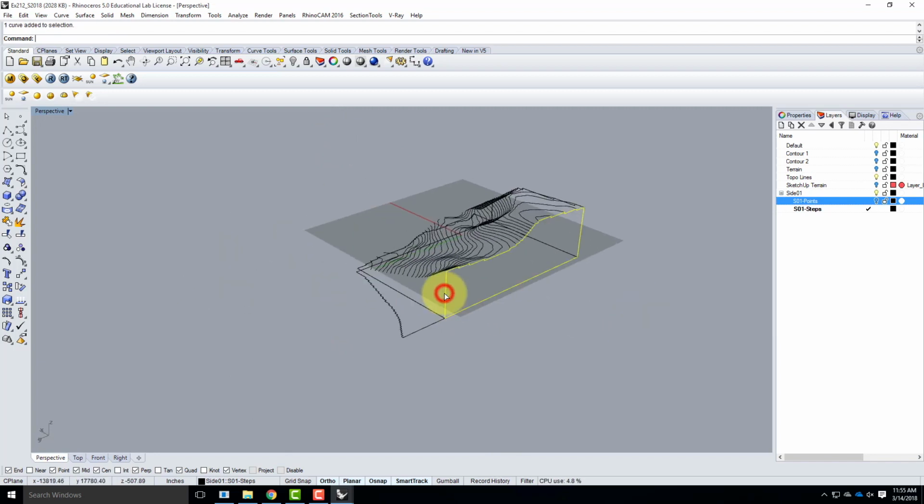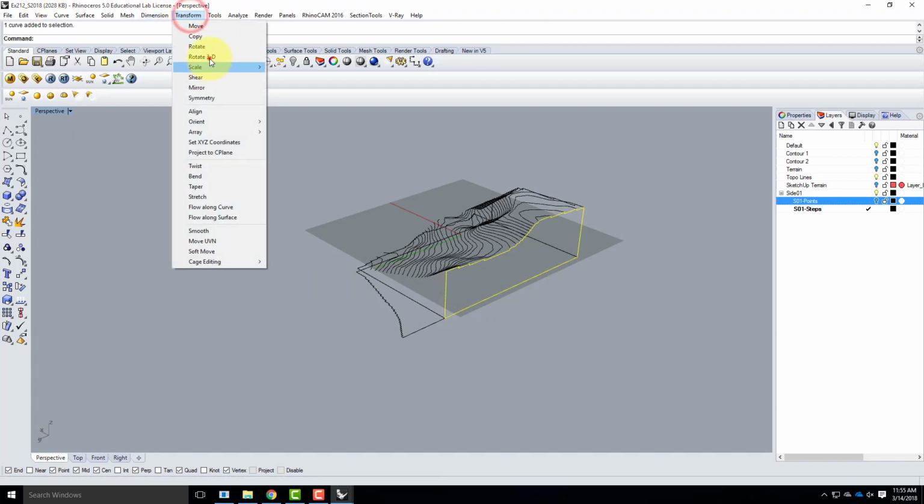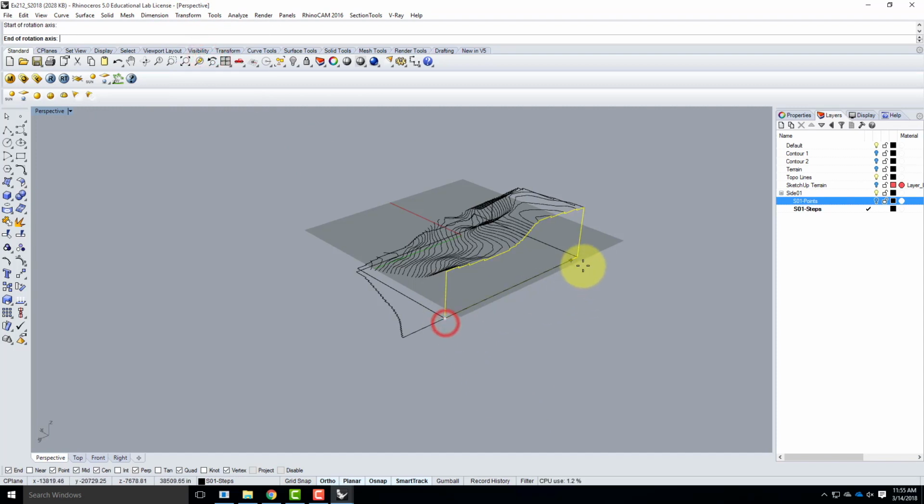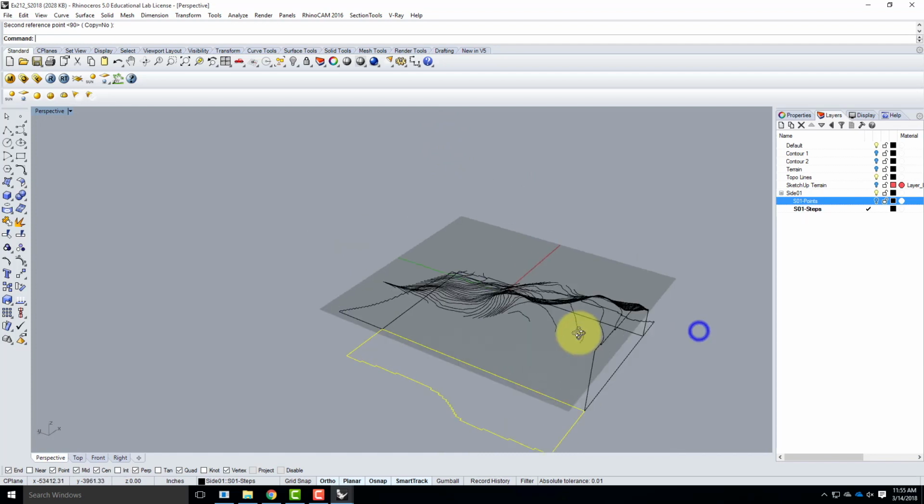It doesn't matter whether you fold them in or fold them out. Logically, it seems like people fold them out. You just have to make sure they're all the same. Don't fold 2 of them in and 2 of them out. That'll get you screwed up. So we'll repeat, Rotate 3D, there to there, straight up, and we'll fold that one down.